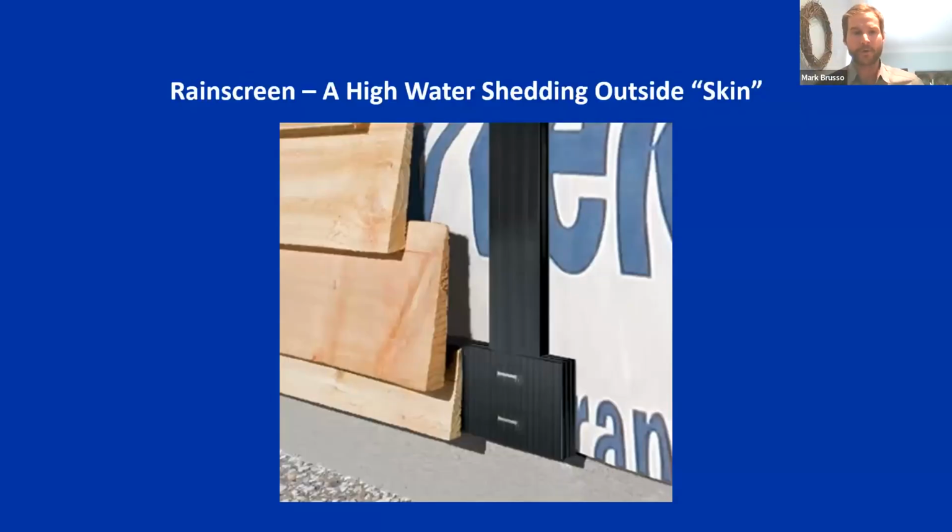So one of the first components is that rain screen has a great outside skin that sheds water extremely well. It certainly doesn't have to be something high tech. It can be something as simple as overlapping board. This diagram qualifies here as a rain screen outside envelope. Something like a rough pine that is shiplapped can qualify as an outside rain screen, something that will shed water effectively.